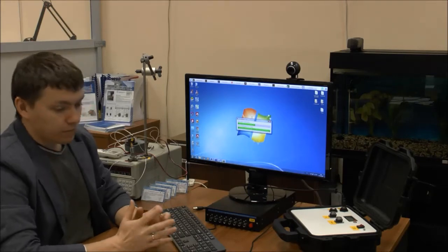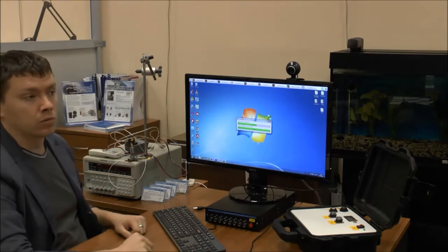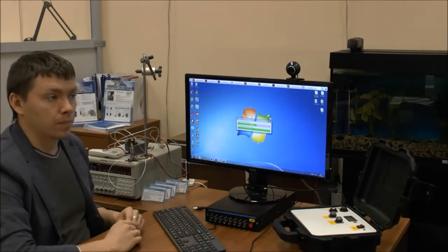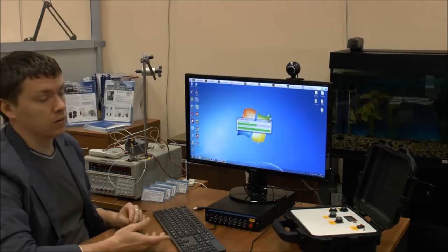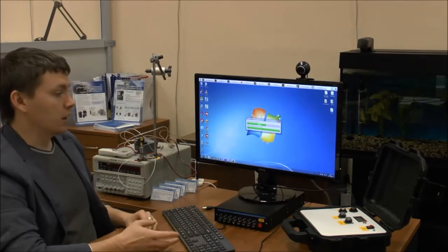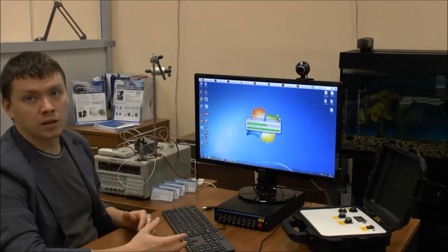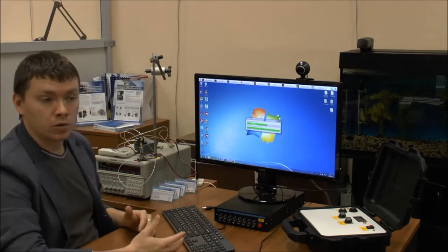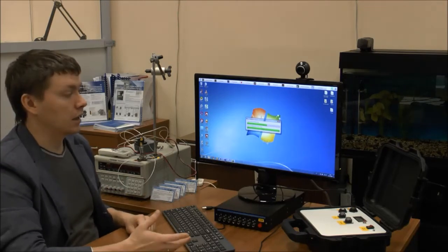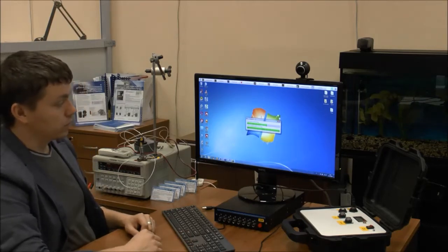Signal processing is performed using MASW method. So we try to cause surface wave at the SP area. And the wave is then sequentially registered by the seismic streamer sensors. Since the sensors are located at different distance from the shot point, the time delay in the event detection is different as well. That is the very essence of this method, which will be further explained when we study RadExPro software operation.